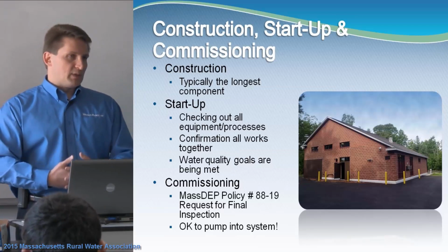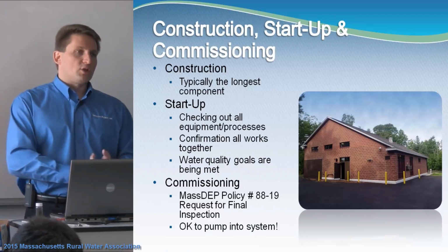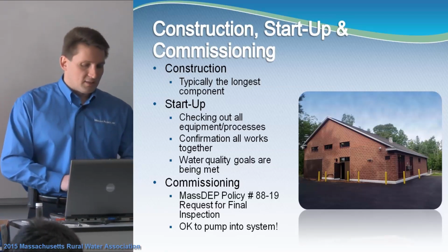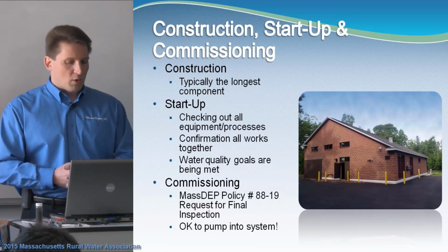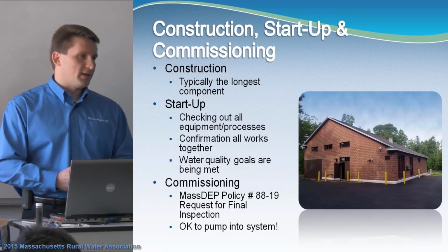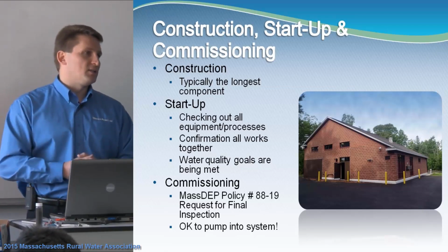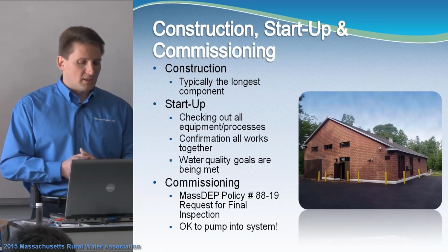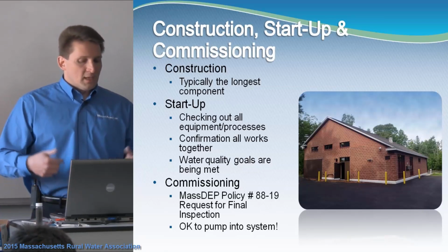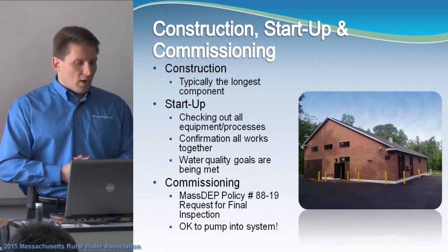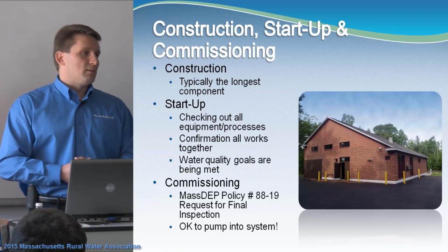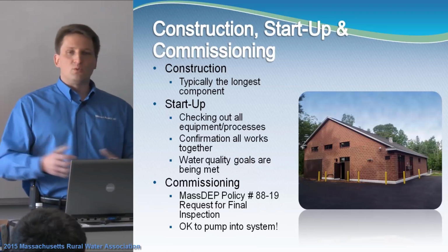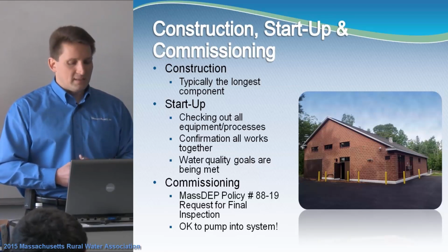Once the facility is built satisfactorily, you've got to go through your startup process. In the startup process, you need to check out all the equipment and all the processes. You want to confirm that it's working and working well, and that the things that talk to each other to tell the backwash to turn on and the pumps to turn off are actually doing what they need to do. And then you start actually running through some water, pumping it to waste, making sure that the treatability goals are being met. And once you do have that confidence, that's when you call the MassDEP.